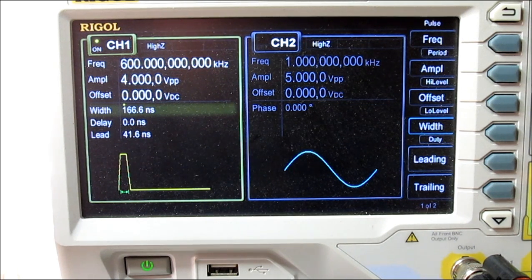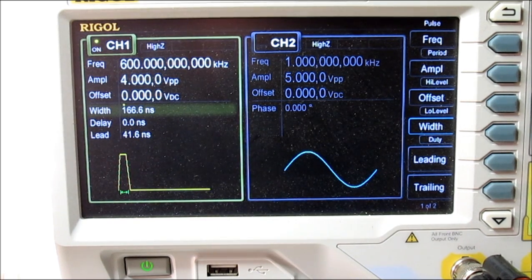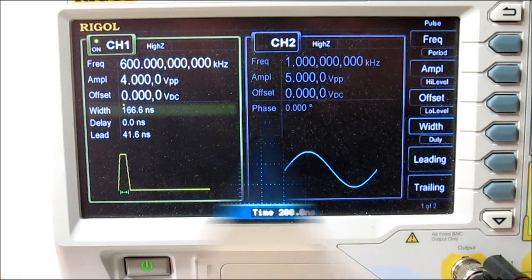Anyway, in this case we've got the frequency set to 600 kilohertz and 4 volts peak to peak, no offset. The rest of it is pulse width, and I think the duty cycle was like 10% until I started playing with the pulse width instead. It was just to make the ringing waveform on the oscilloscope look like a nice, clean ringing waveform. So that's the tracking generator setup.